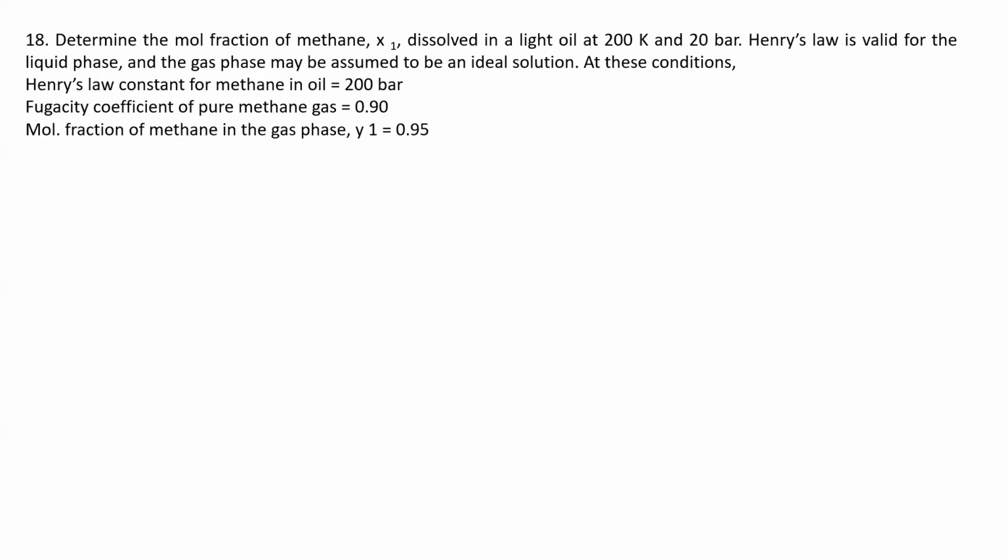So T and P are given. Henry's law is valid for the liquid phase, and the gas phase may be assumed to be an ideal solution. So ideal gas is there, so phi I will be equal to 1 everywhere at these conditions.